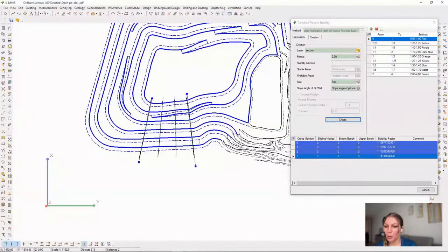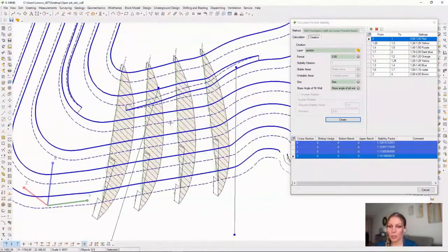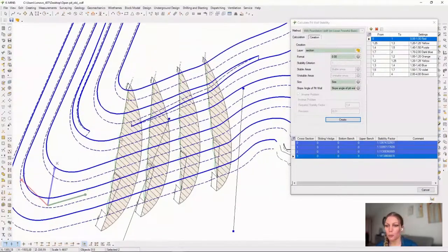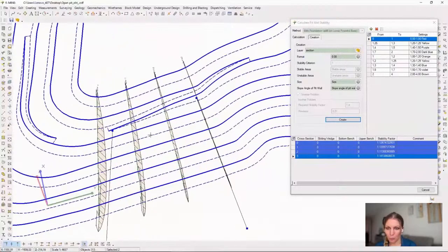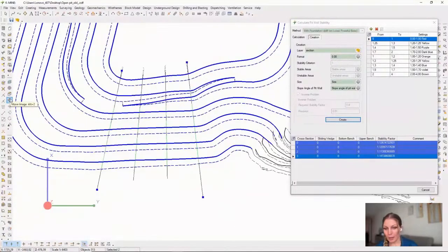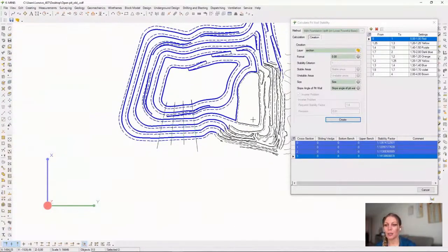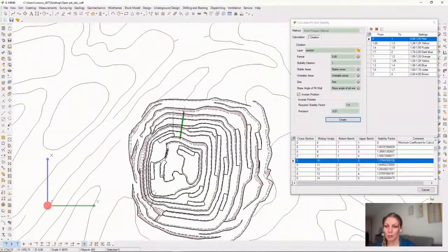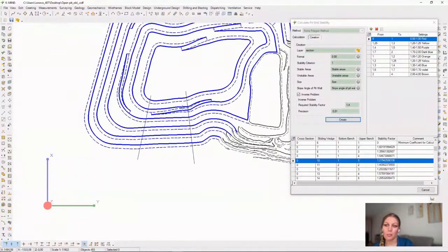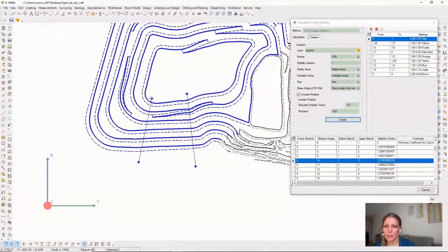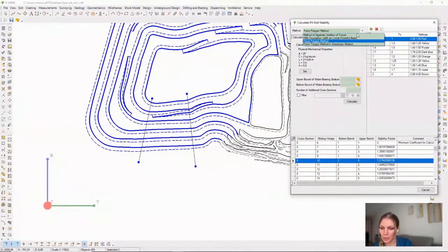The result obtained while calculating slopes on a weak foundation covers only the slope from the first lower edge, which is basically the boundary of the rocks of the weak foundation by default, to the last upper edge that intersects the calculated profiles represented by a polyline. This method is incredibly useful in accurately assessing the stability of slopes and ensuring the safety of individuals and equipment in this area.